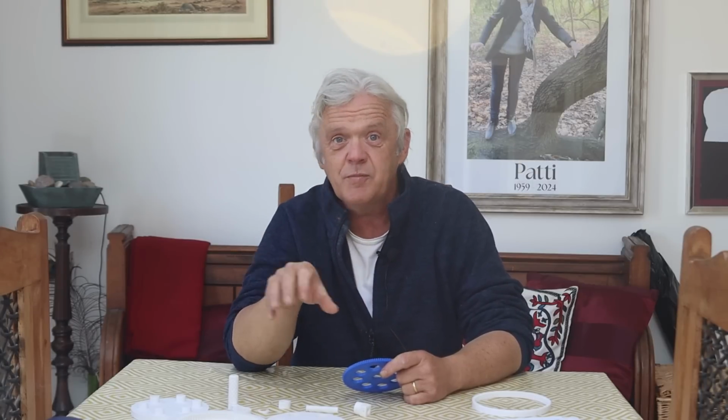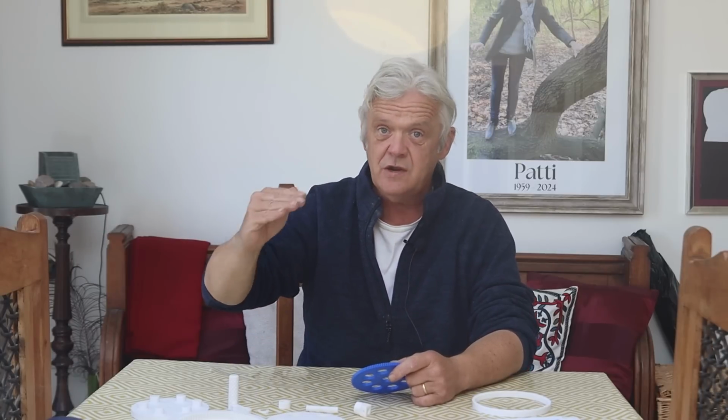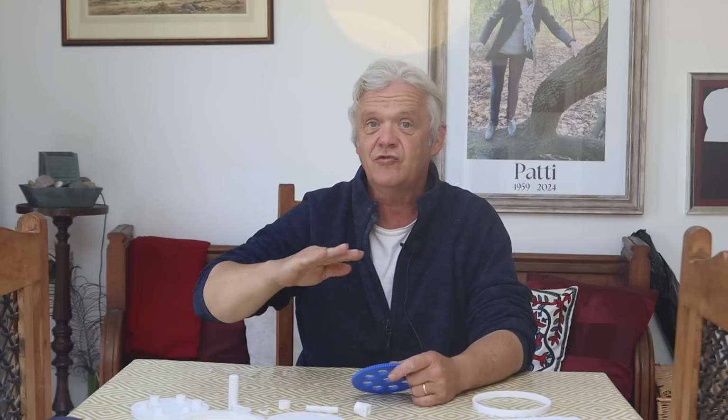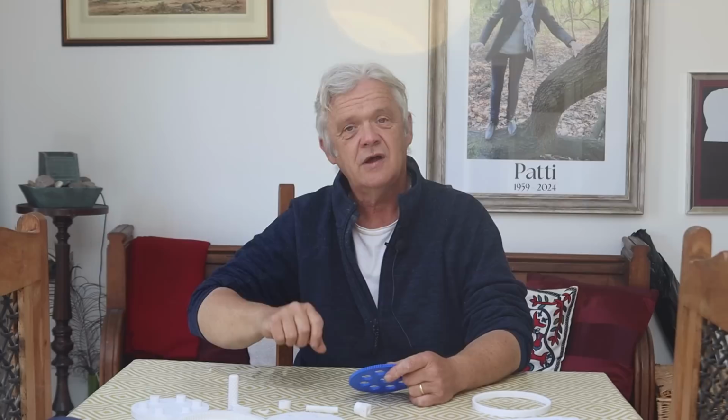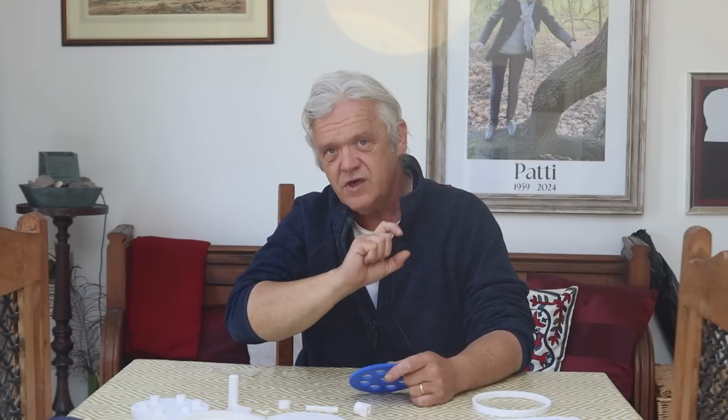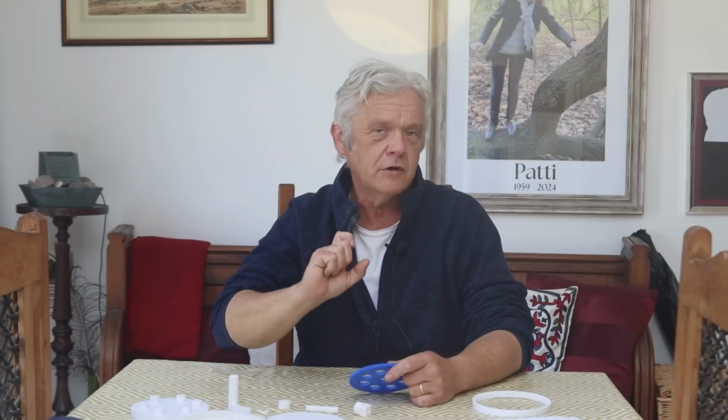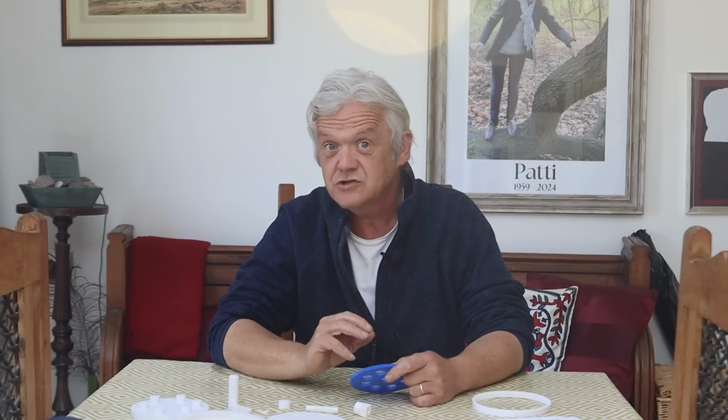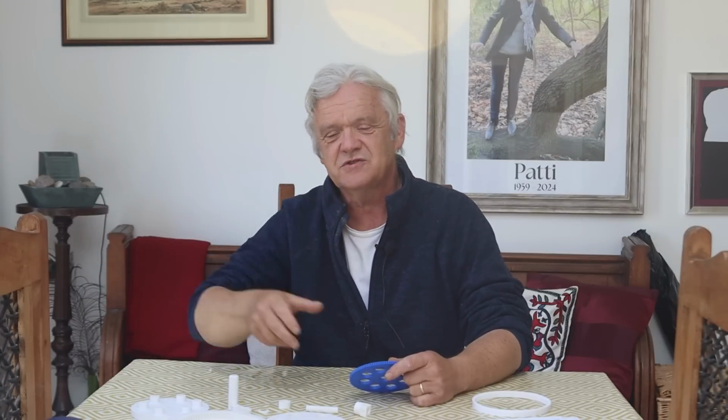Now, another option here is never to make a sketch too complicated. If you put a billion items on a sketch, trying to do a whole machine out of it, you're going to lose track. Remember that process of breaking down a machine into a mechanism, into a part, into 3-layer sketches, and it'll help you to keep track of what your constraints are and make sure you've put the constraints in. Later, that's going to help tremendously. Right now, I think people find it hideously frustrating.